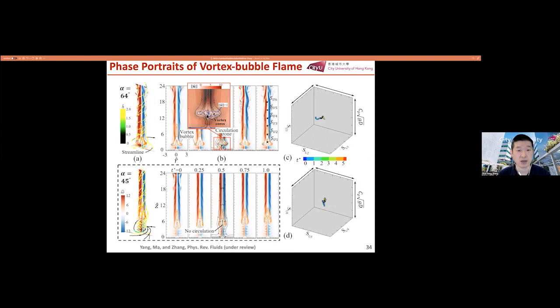So this is a vortex breakdown case, and actually we got this result a long time ago. At that time, we were quite interested in what some of our colleagues in this community discovered, the blue whirl. At the beginning, I recognized that to computationally reproduce a blue whirl, the first step, we must introduce finite rate chemistry, and then due to the lift off, once the flame is lifted off, there's a chance for the fuel and oxidizer to mix in the upstream and form the premixed flame structure. So I believe that a couple of years ago, they already published something, but we never got the chance to publish our result because we didn't get a very good, beautiful theoretical interpretation of what's going on here.